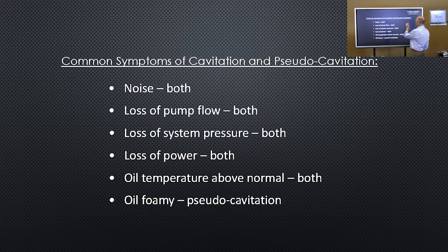Both cavitation and pseudocavitation will yield noise. The pump will be noisy. Now, it's hard to discern from the noise whether it's cavitation or pseudocavitation. There might be a slight difference, but noise is not anything that I would use to determine whether I've got cavitation or pseudocavitation. Next, both will lose flow. Whether you're cavitating, meaning you've got starvation, or aeration, you're going to lose flow. Next, I will lose pressure, which means I'm going to lose power. Either one. If I lose flow and or pressure, I'm going to lose power.